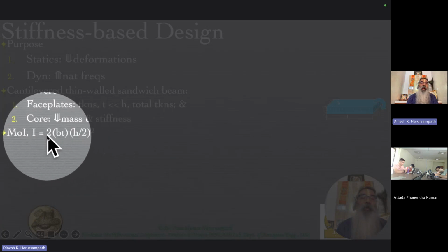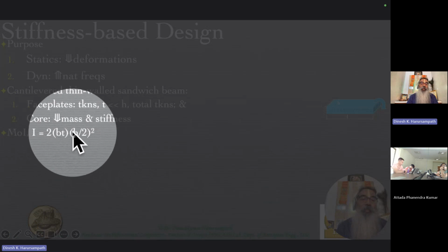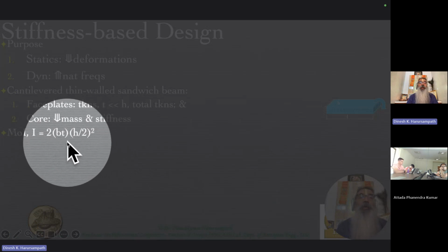Now, this is an important factor. We will look at why it is important in a later class, but right now, let's take it for granted that in a bending problem, this is one of the geometric features of great significance. In fact, we discussed this qualitatively when we considered why we have I sections, that is, for a lot of beams undergoing flexural load as the major load, we have the I section as a dominant geometry because we want to push the material away from the center or so-called neutral axis so that it can take much more stress and therefore counteract much larger bending moments.